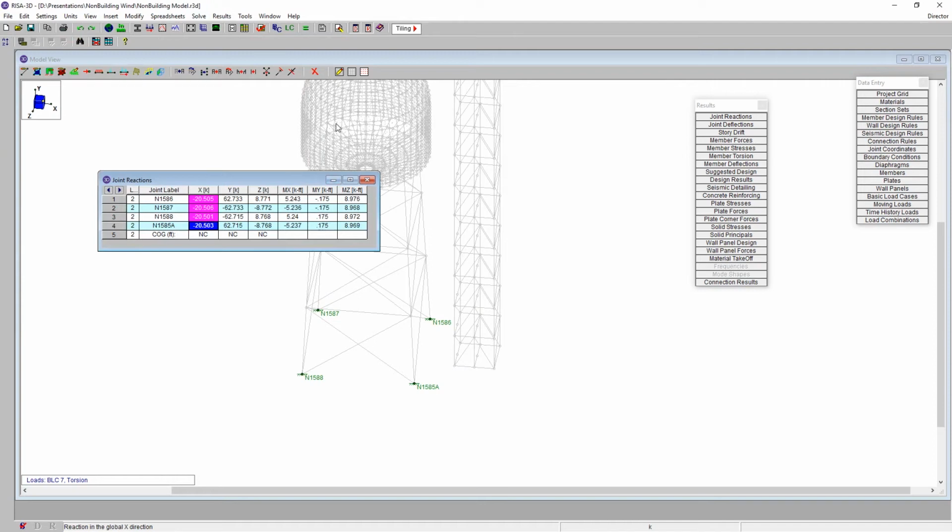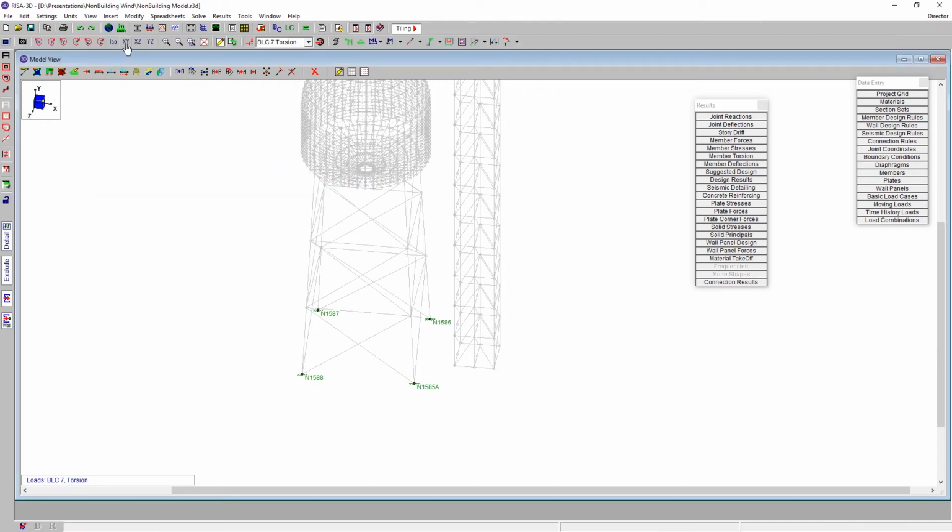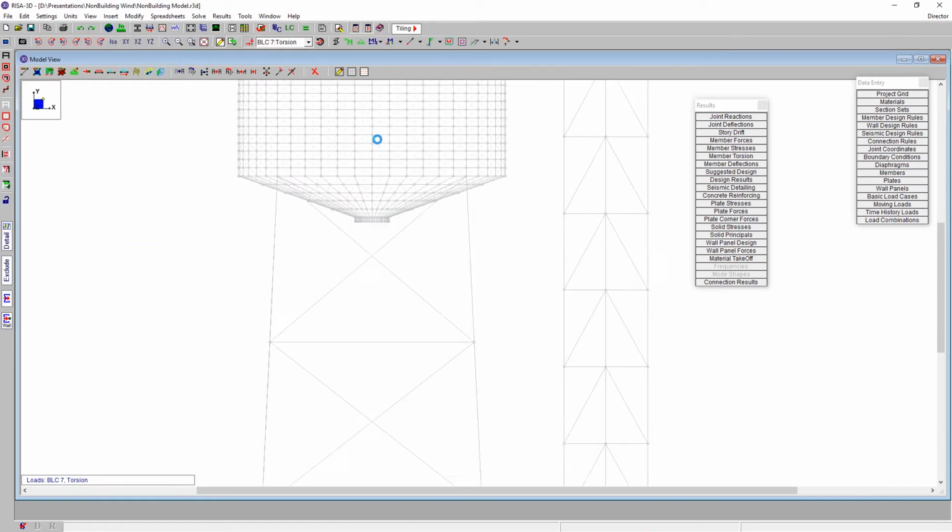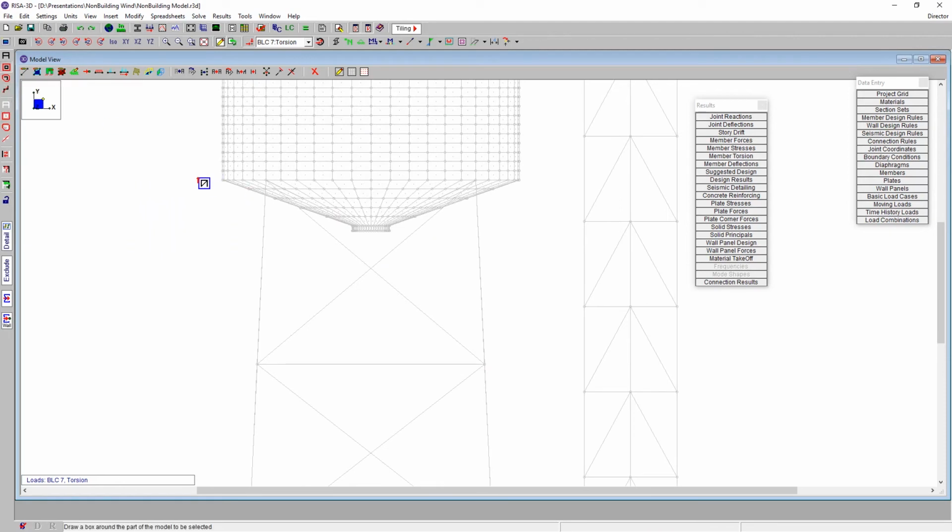That's about 82 kips of wind force that's on this tank. And what we saw was that the torsional load that we need to apply on here was 0.003 times that value. And so what we're going to end up with then for a torsional load is about 246 pounds per linear foot needs to be applied around the circumference of this tank.